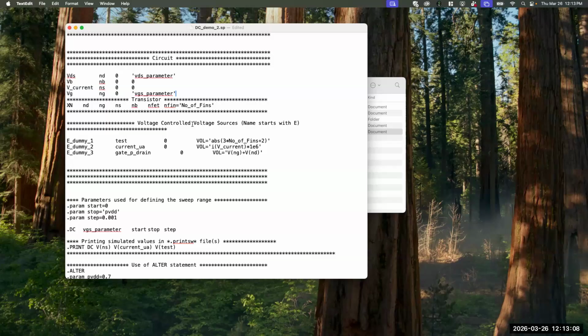So you see an option on the side to click on, like in Cadence for example: voltage of node 1, voltage of node 2, voltage of node 7, all the node voltages are available. Also current through V1, current through VDC, current through whatever voltage source you have connected. That's why we deliberately connected random zero voltage sources, just in case I need to see the current.